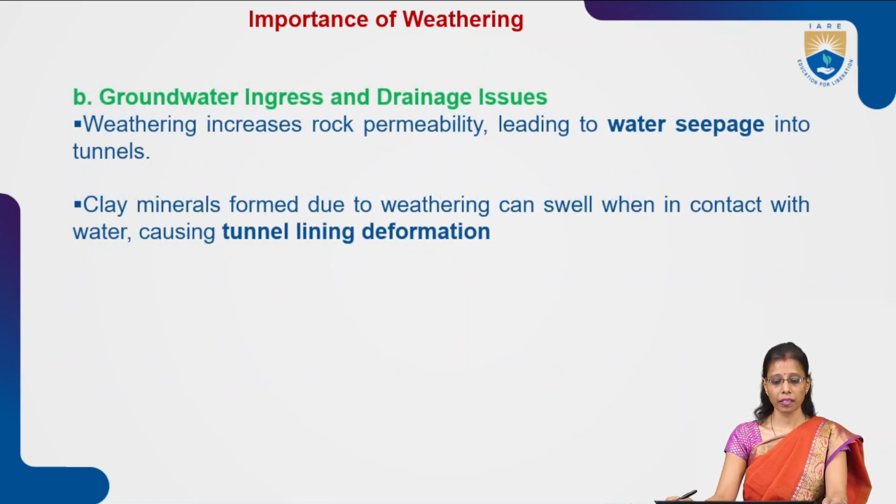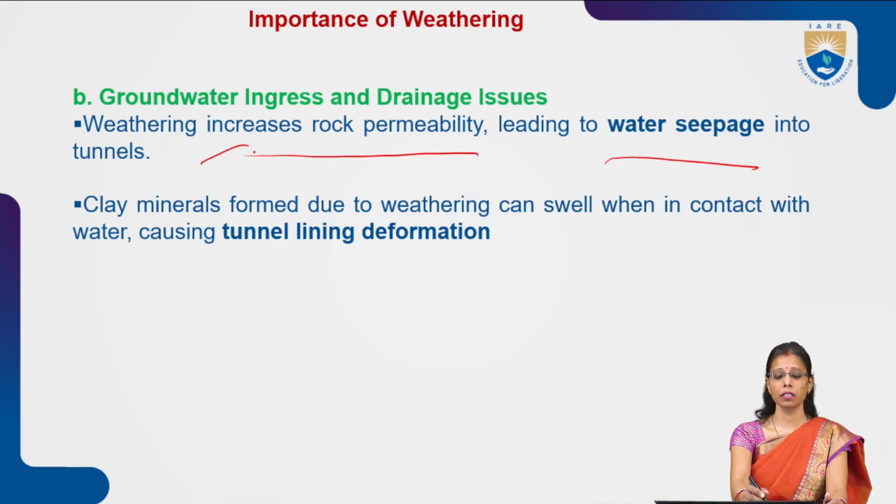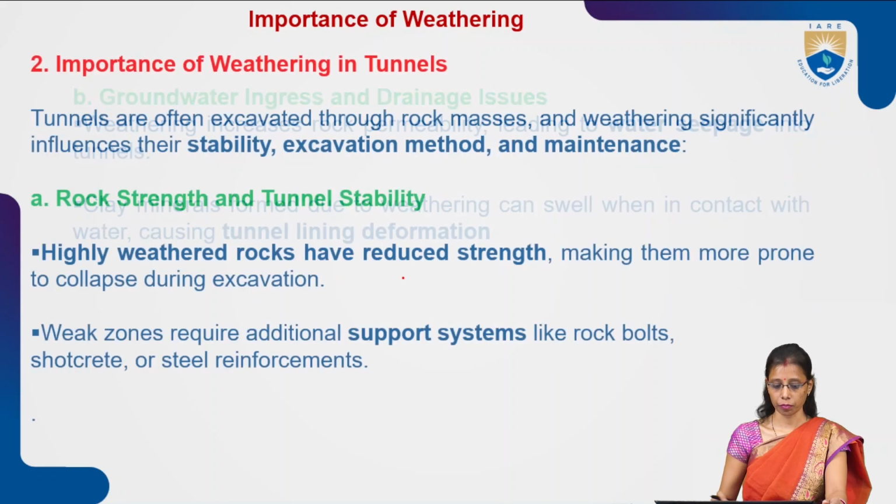Now, groundwater ingress and drainage issues. So here, groundwater ingress and drainage issues will also happen. Weathering increases rock permeability, leading to water seepage into the tunnels. Clay minerals formed due to the weathering can swell when in contact with water, causing tunnel lining deformations.